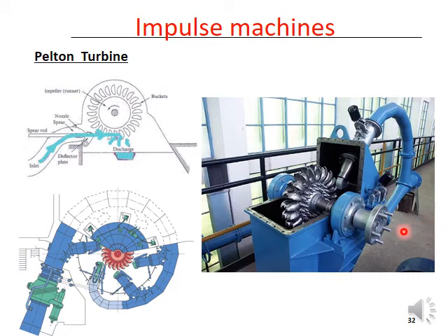An axis is here. This axis is connected to the generator. So this is a common Pelton wheel installation. This can be vertical axis or horizontal axis. In this case, this is a horizontal axis installation. We have Pelton wheel installations in Sri Lanka, like in Laxapana hydropower station or in many small hydropower stations. Pelton wheel turbines are the most efficient when you have a very high head for your installation.